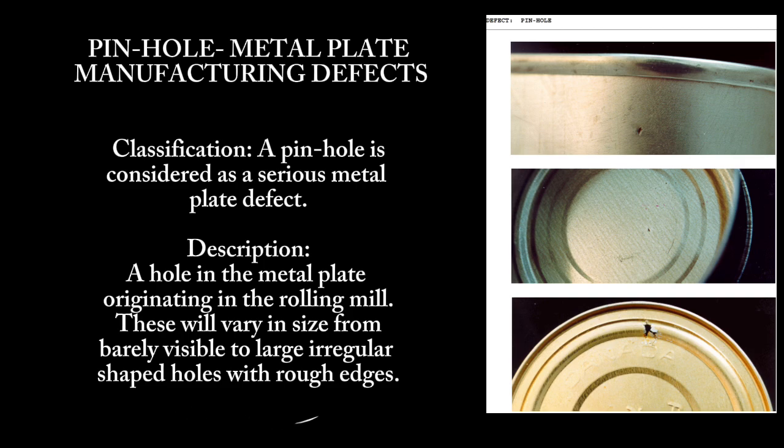The primary cause of pinholes is the presence of foreign particles such as dirt, slag, or other contaminants that become embedded in the plate during rolling. These particles do not bond with the surrounding metal. If the particle is large, it can penetrate through both sides of the plate.